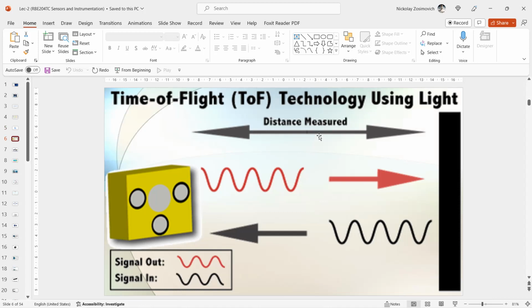So not only the characteristics of the sensing method, but also the properties of the measurement object, like the kind of liquid and shape of the tank, and the environment should be taken into account too. For the tank system, the acoustic TOF method, time of flight, could be an excellent candidate because of its being contact-free. In this phase, it is also important to consider methods to reduce such environmental factors as temperature.